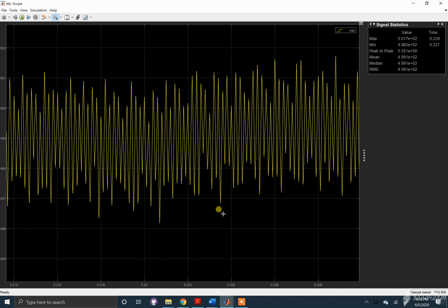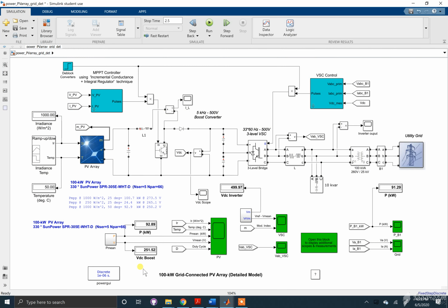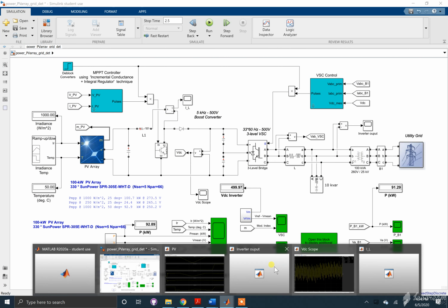the boost converter's output voltage, which shows that with this capacitance you get a voltage ripple of about 4.5 to 5 volts, which, when the numbers are crunched, produces a 1% voltage ripple, which is completely acceptable for a typical boost converter. Going on to the inductor, we can take a look at the inductor current, because the inductor current